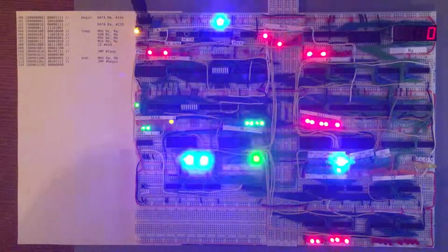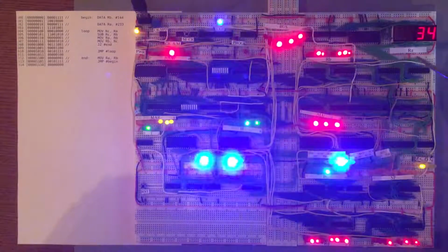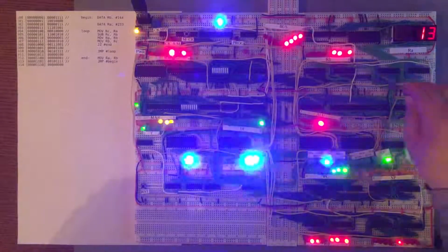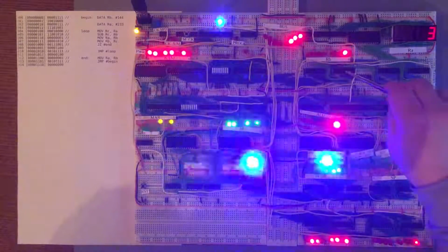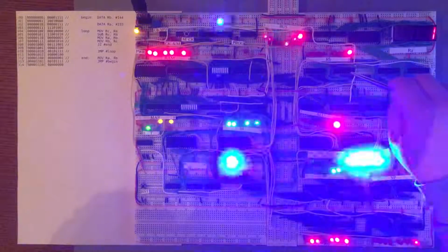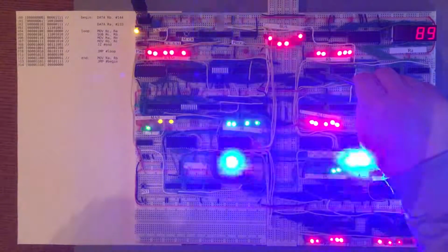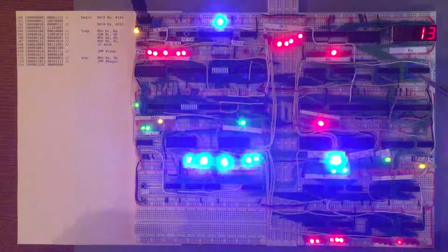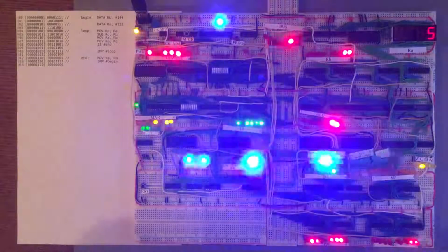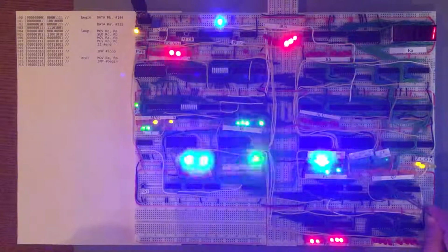So that more or less wraps up our episode for today. So we've had a look at our registers, the A register and the B register. So now we know that each register is implemented by 2 chips. There's an actual register chip, which stores the values, and then there's a buffer chip, which enables the contents out onto the bus. And so we have that for the A register, for the B register, for the C register, for the D register, and also for the stack pointer.